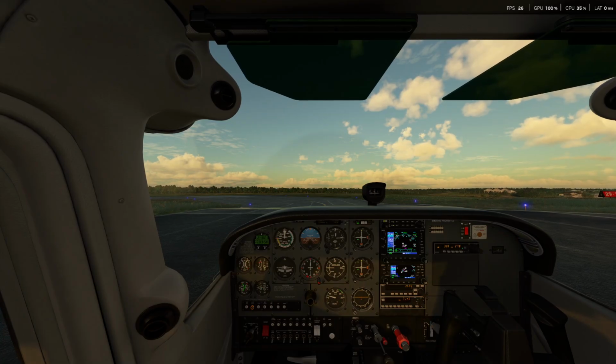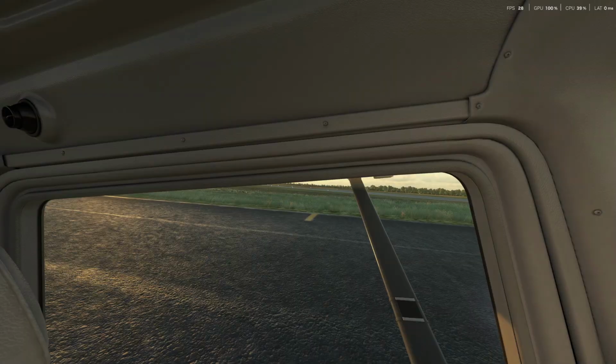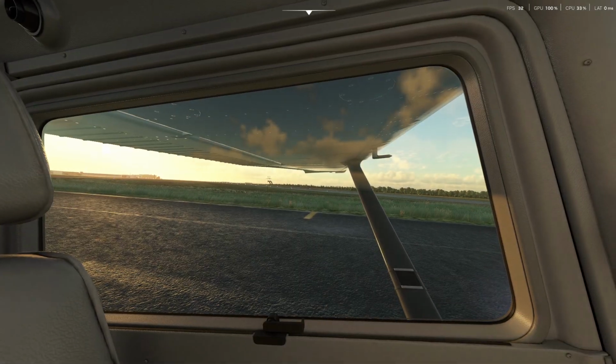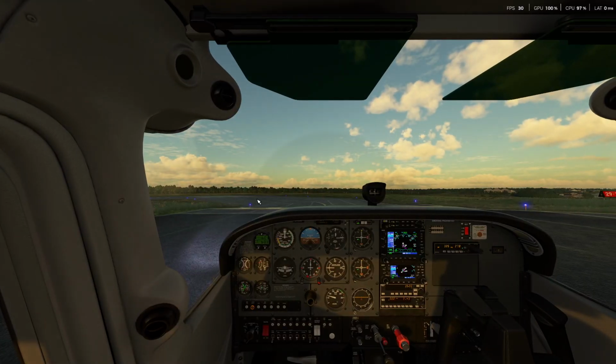Alright, before takeoff checklist, holding short. The time we're going to record, and change the clock here back to local. It's 0603. Compass and heading indicator, we'll verify that once we line up. We'll say we're cleared to line up now. The transponder will go to alt. Wind, taxi lights, strobes, the wind direction. We can confirm the wind sock. I guess we have two of them. The wind's as confirmed by the IPS.